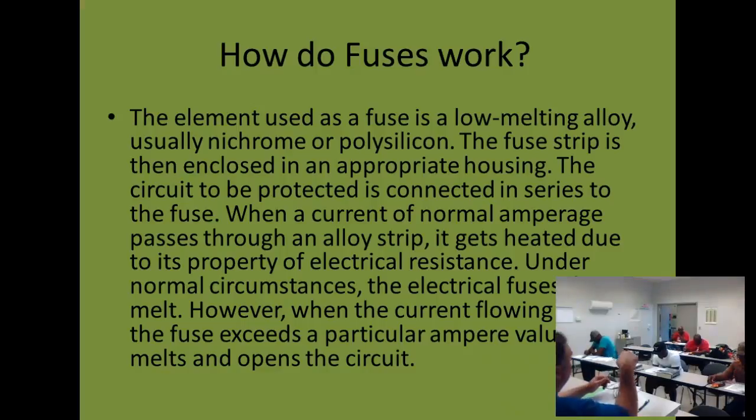So what did the paper just say on a fuse? 0.1. So if it goes above that, they're saying time to get a new fuse. Yeah. They're not saying there's not a path. They're just saying that path has a little resistance and it's going to create heat. And if I create heat, I'm going to have problems.